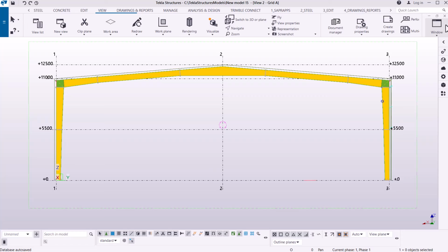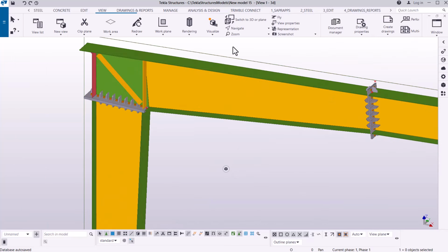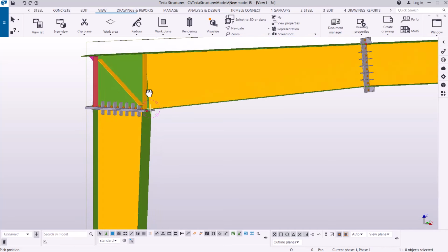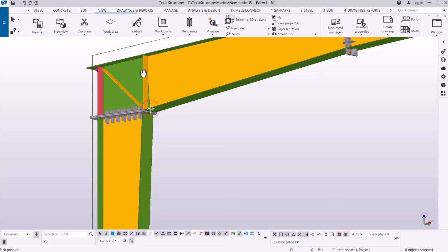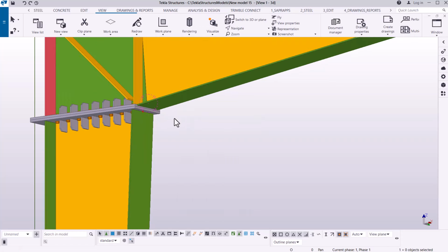Now I'll press Control Tab here just to switch to isometric view, and I'll come to navigate under rotate with mouse. I'll come to navigate, then rotate with mouse after picking my rotation point. Now I want to pick my data point where I'll generate some points there to help in creating a tab that will be helping us in adding more details to make it a Corbel that will be suspending the crane beam up there.